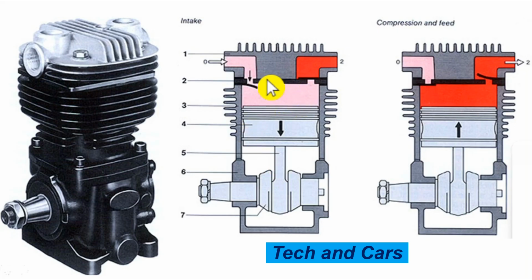If you find excessive moisture after draining the tank, that is also a sign of trouble. If you constantly find a large amount of water in the air tank, even when draining it daily, that is also a sign of trouble. This is usually caused by a failed air dryer. The air dryer has to supply moisture-free air, and if the purge valve is not working properly, if it is stuck, that can also cause excessive moisture in the compressed air.